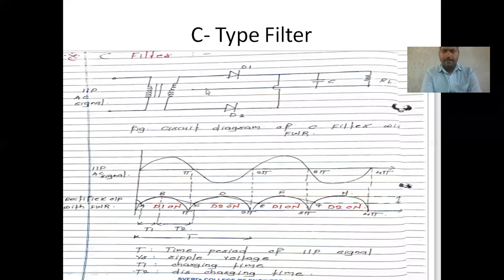So during this cycle, plus minus, plus minus. At the first time, minus voltage appears across D2, so it does not conduct. Only the diode D1 conducts, so positive voltage appears across the capacitor, right? So this will happen during this positive cycle. See, during this positive cycle, diode D1 is turned on, so your positive cycle is coming across your load, right?